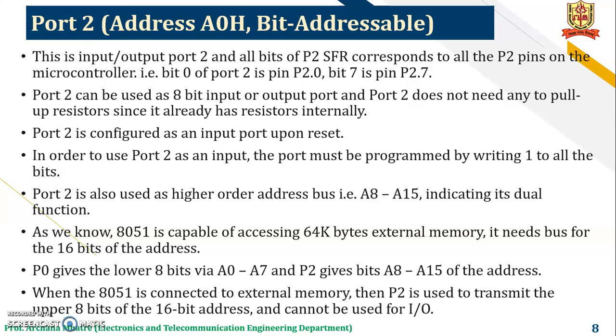So P0 gives the lower 8 bits via A0 to A7, while P2 gives the higher 8 bits via A8 to A15 of the address. When the 8051 is connected to external memory, P2 is used to transmit the upper 8 bits of the 16-bit address, and it cannot be used as an input-output port.